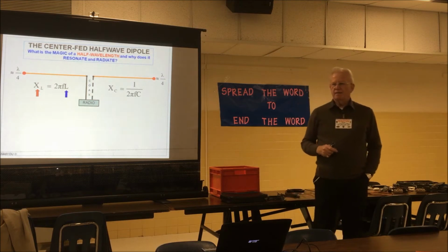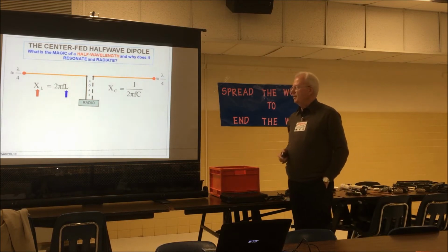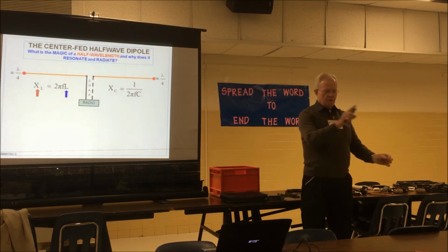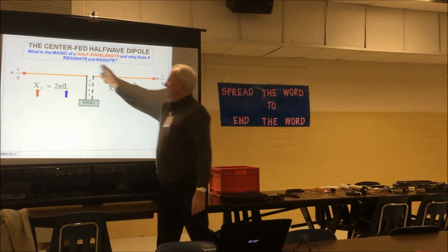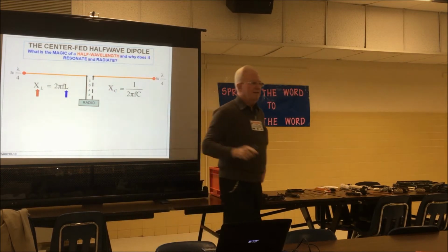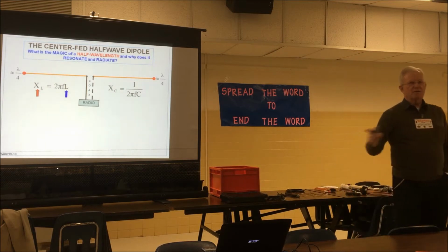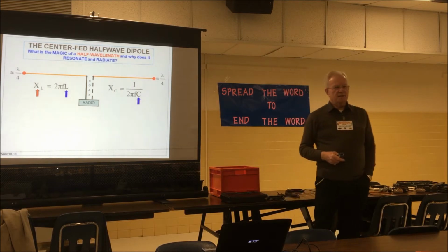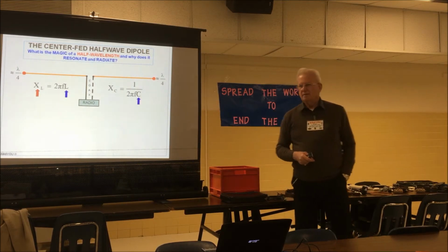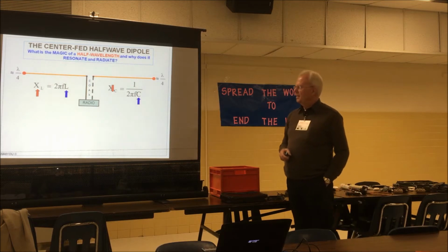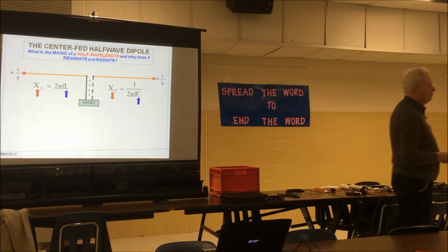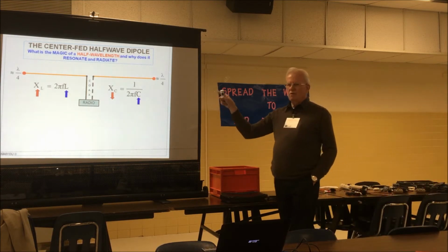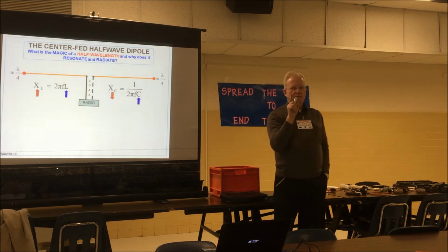On the other side here, the antenna also has capacitance. The farther away the 2 wires are, you have a capacitor here, and a capacitor here, and a capacitor here, and a capacitor here. And of course, as it goes down the wires, the capacitance gets greater. Now it gets crazy. As capacitance goes up, capacitive reactance goes down. It is a negative number.